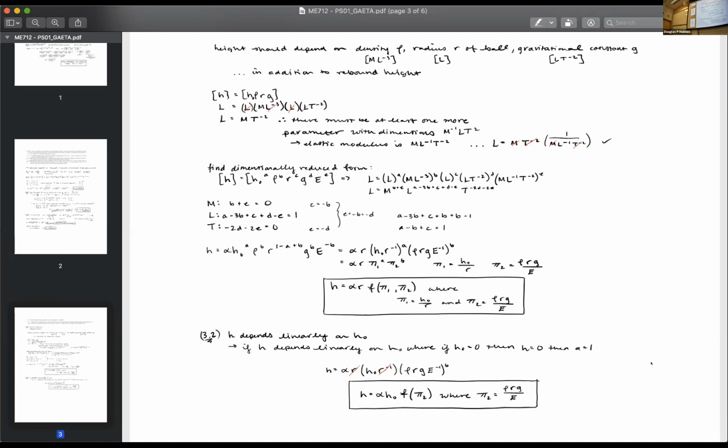And I think you don't necessarily need to address that, but once you got here and tested it and it seems like it works, if you're going to write the paper on this, you want to think, okay, what did I leave out? Again, playing the lawyer, how could I break this? Well, I could break this by dropping my bouncy ball onto a huge bath of Jello. I don't really expect it to bounce back as high. Why not? In that case, the modulus of the surface it's bouncing on is significantly softer, or maybe even comparable to the modulus of the object that's falling. And so that's part of the assumptions that you would probably address in writing, if that makes sense.